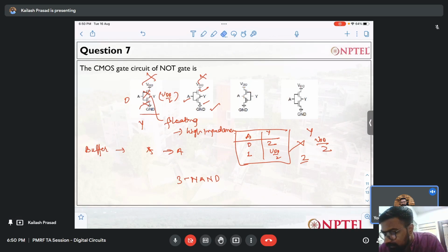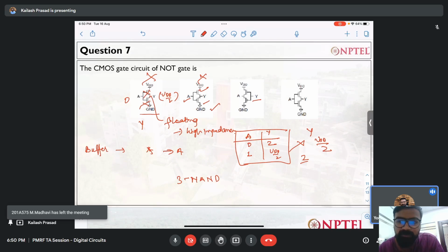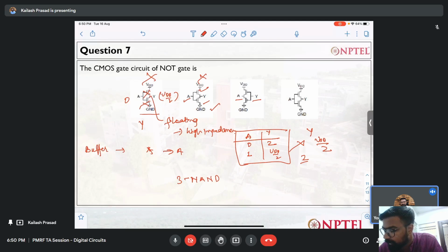So it means that Y cannot be an output, rather Y will be an input. So this circuit is logically wrong if anybody asks what the expression of Y will be. But if I ask what the expression of A will be, then Y will be an input and A will be an output, and we can have some expression there. So A can be an output.